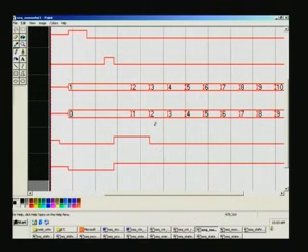Why that happened is the code was different. I did not take that reset counter D as an asynchronous way of setting in this. So earlier what I had done is that reset counter I had taken inside itself. So when reg is 255, I make a decision only there.